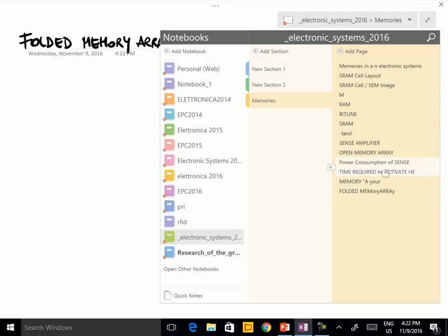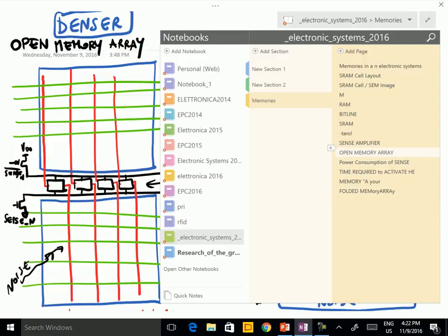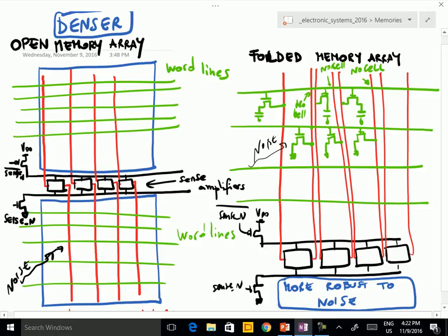just let me look at this part. You see that the difference is that in the folded memory array, you have a memory cell only in correspondence of half of the crossings. And in the case of the other half of the crossings, you don't want anything. You do not want an electric contact, and in practice you only want electrical insulation.